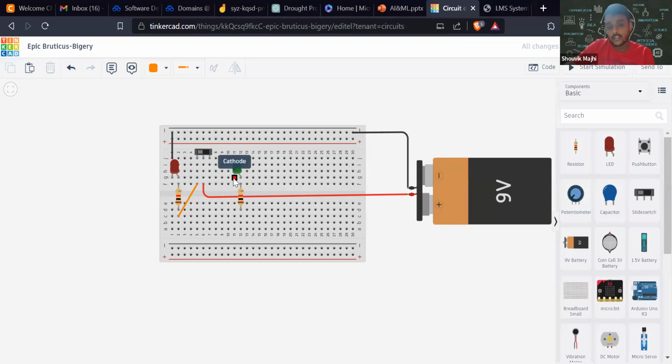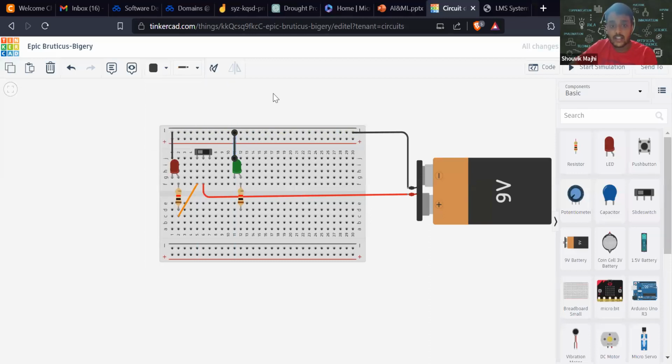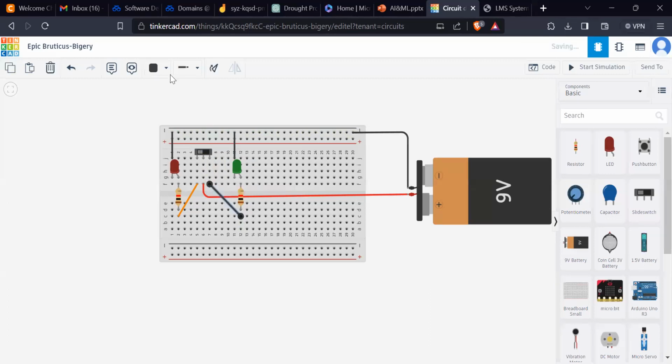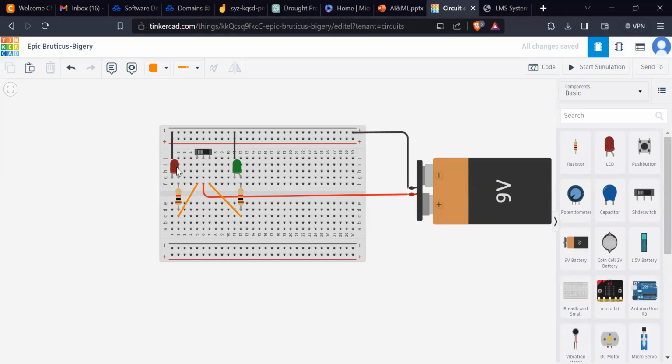Now I have this negative side. The negative side should go to the negative side of the battery. So I have this negative side ready, internally connected in the breadboard, connecting the negative side of the LED to the battery itself. And again, the positive side, or you can say the side which has a resistor, should go to the terminal 2 of our switch, like this. So let us color code it. Okay, this makes the circuit complete for both the red LED and the green LED.